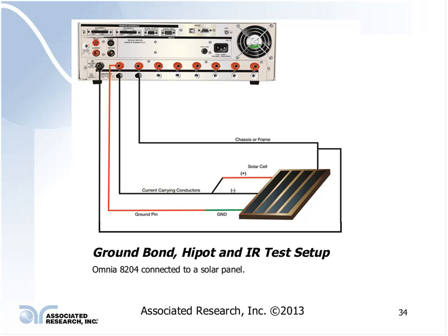If I was testing reverse polarity, then I can automatically open those relays again and flow right into the test where I apply high potential here to reverse the polarity and return on my mains conductors. And that pretty much completes your test cycle. Since the IR test is the same thing, you would actually set the exact same relays for that test.